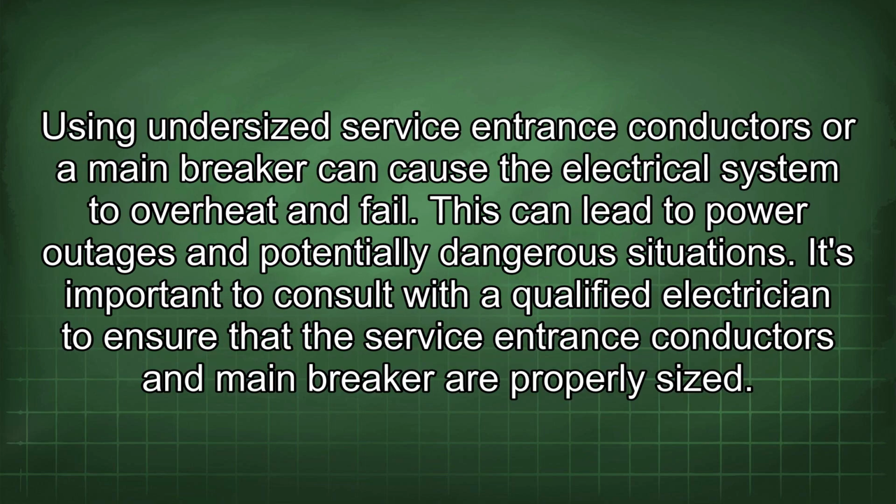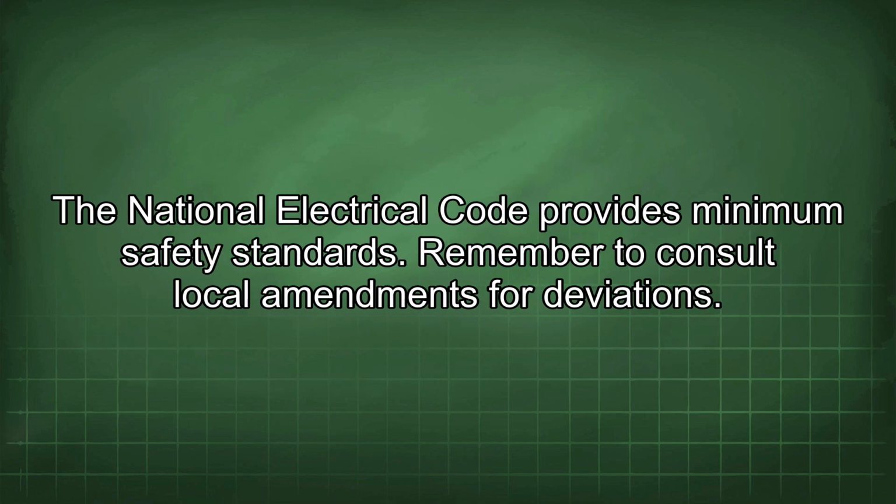Using undersized service entrance conductors or a main breaker can cause the electrical system to overheat and fail. This can lead to power outages and potentially dangerous situations. It's important to consult with a qualified electrician to ensure that the service entrance conductors and main breaker are properly sized. The National Electrical Code provides minimum safety standards. Remember to consult local amendments for deviations.